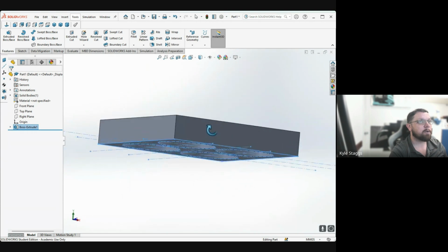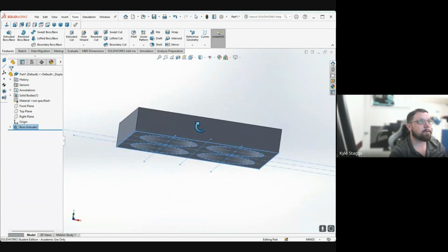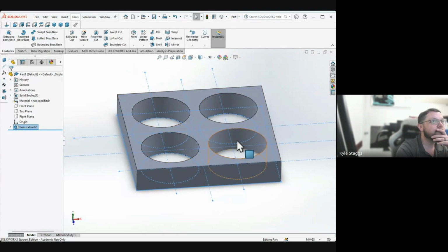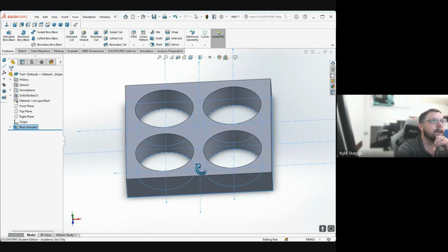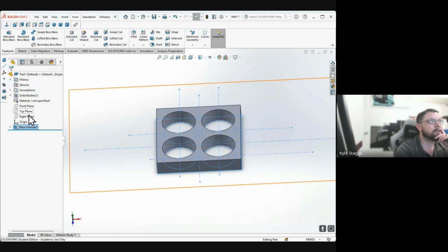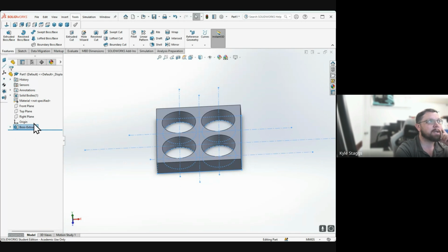Then I'm clicking the scroll wheel down to be able to show you in 3D what that looks like and what that rotation looks like. So we have it in 3D, and that's the simple example of the extrusion process. You can do additional extrusions from that base sketch. We'll deal with how to do that later because we're constrained for time today.